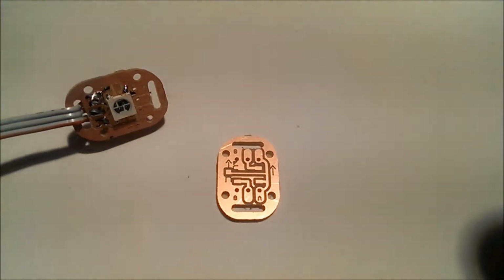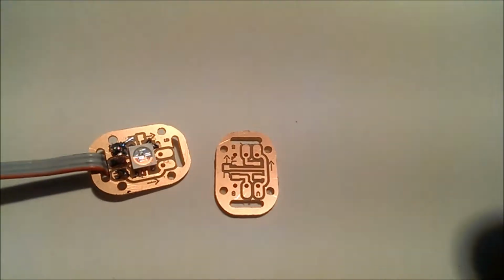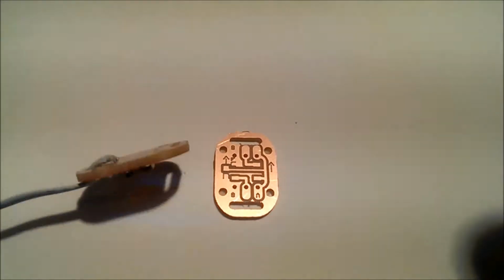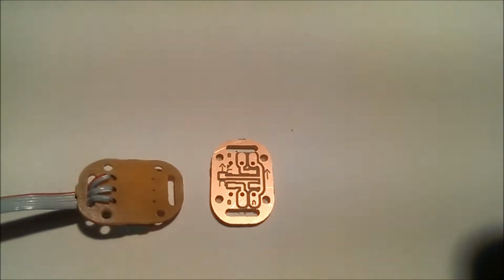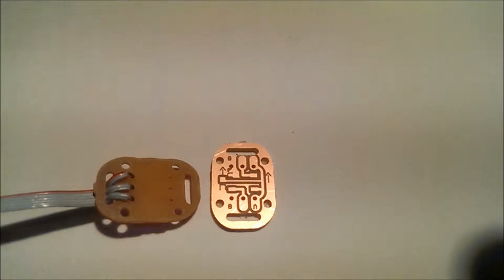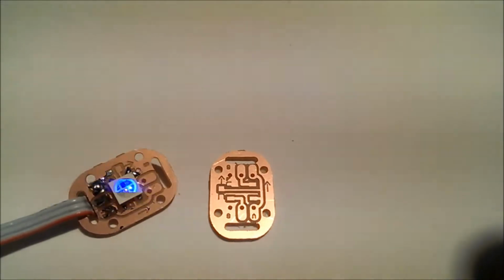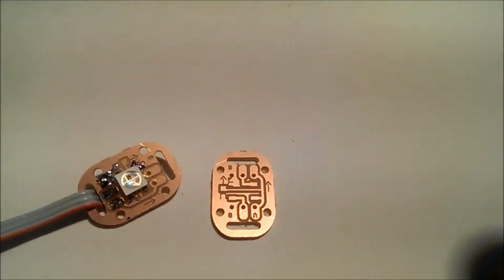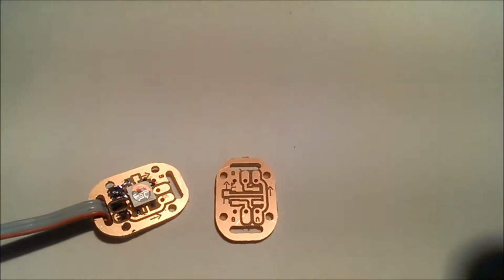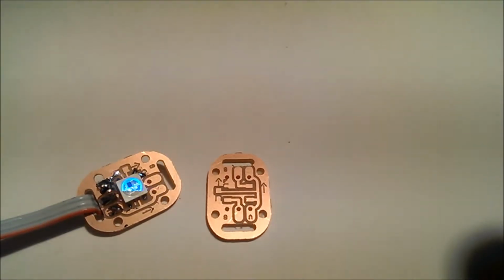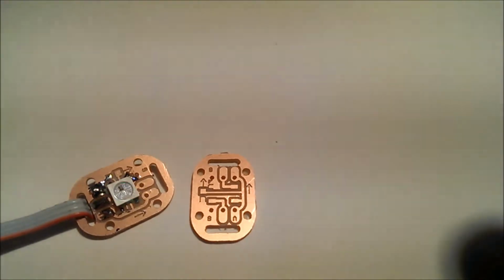And here is one with a NeoPixel soldered onto the board. And actually those tabs on the side work really well for holding in my cable. I've just been using ribbon cable. You can get it for fairly cheap, and it holds the wires together really nice for doing long runs. But as you can see, the NeoPixel is working. The pads were a little small for doing hand soldering, so I might actually do a few changes and just make those pads a little bigger. But the circuit works, and that's what I was really concerned with.